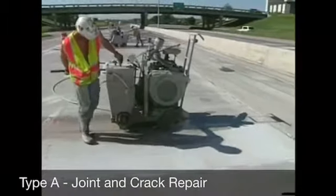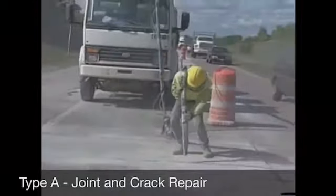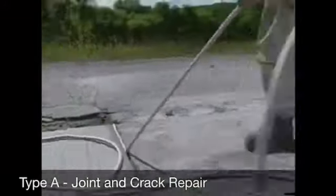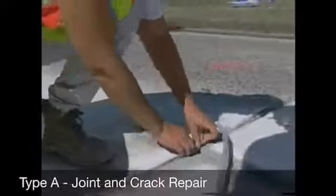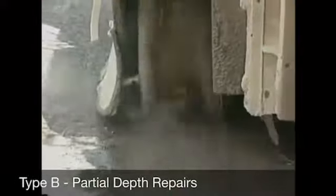Type A repairs involve the rehabilitation of any joints or cracks in the pavement by sealing these with joint sealant. When sealants are damaged, chemicals, solid materials and water can get into the reinforcement system, causing huge problems down the track. These repairs need to occur straight away.